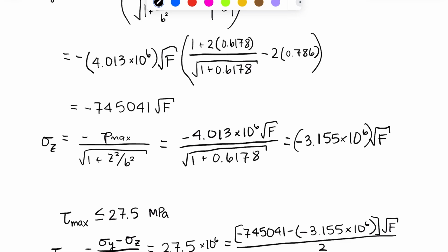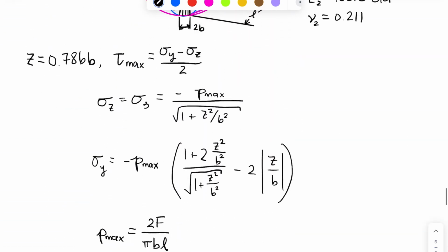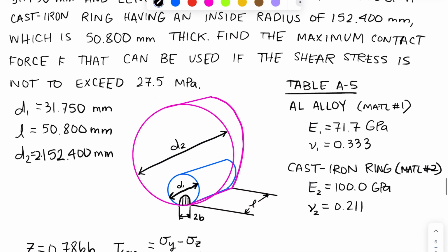So this is very close to a kind of scenario you might have with a rolling element in a bearing. But keep in mind that all of this is still conceptualizing this as static loads, so we are analyzing this ring and this roller as if nothing is moving. When we get to the point where things are moving, we're going to have to develop some different models to deal with that.